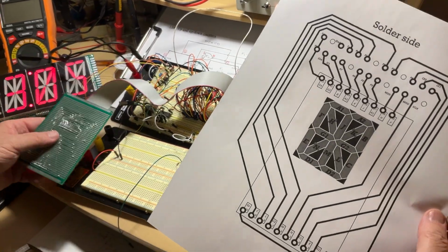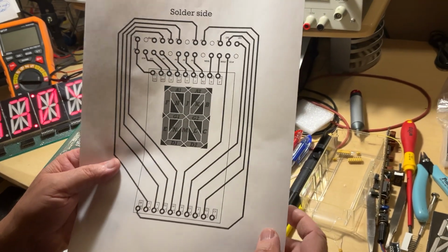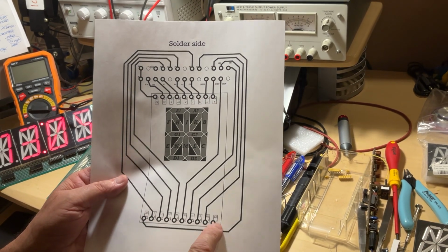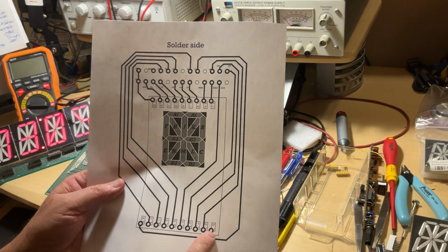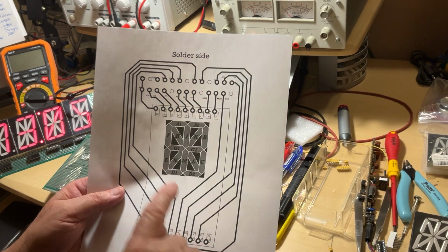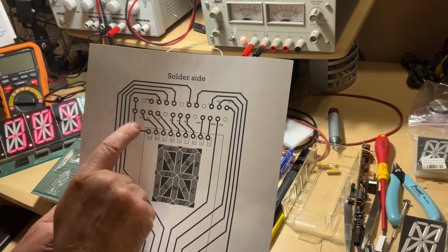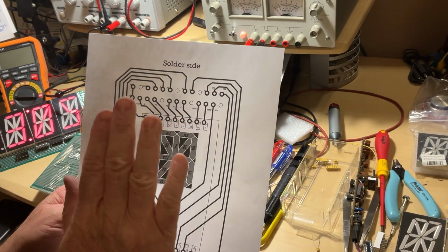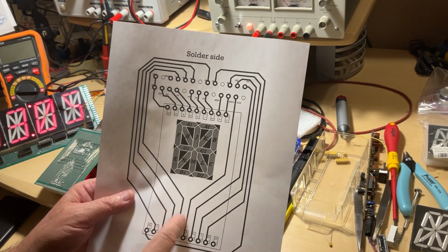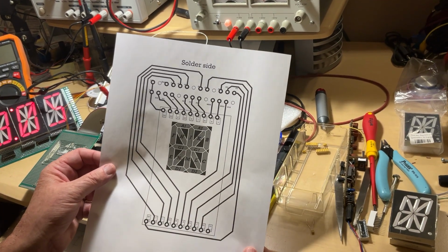And if you take a look at the drawing, you're going to find out that, let's say, pin 10 is the decimal point, DP. Pin 1 is the common anode. Why is there no wiring here? Because the same as this one, you're going to find on the other side, on the diagonal, on pin 11, common anode, and I'm going to use this one. So you can build one such tester, and you're going to be able to test either the common anode, like this one here, or the common cathode as well, okay? So we're going to test them both, don't worry about that.